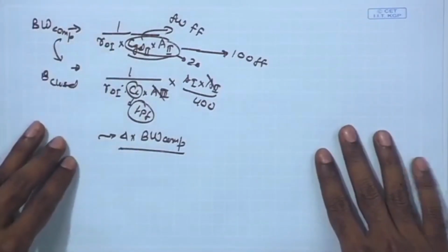Okay, so we can take a short break and then resume our discussion on the remaining point, that is input interfacing with the offset cancellation circuitry. How are we going to apply the two inputs, the ramping input and the sampled input voltage, to our comparator along with this offset cancellation unit? What is going to be the best way, and how are we going to place the sampling capacitor which is sampling the input data? We are going to look into that next.